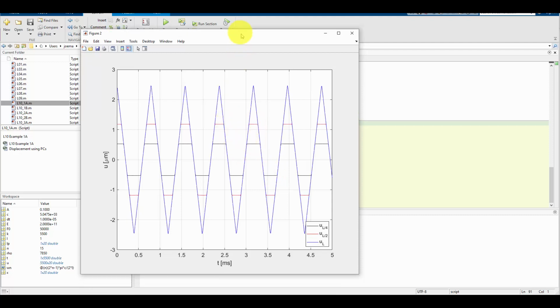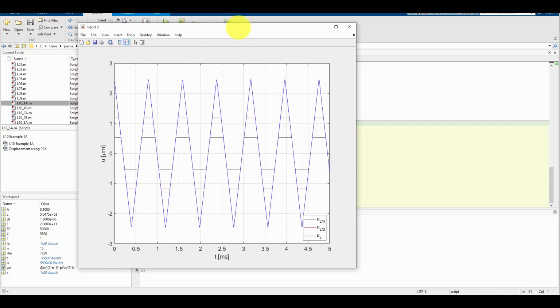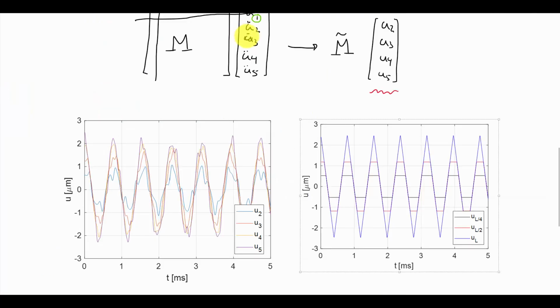So let's compare these more side to side though. All right, so I'm comparing just those output graphs now so we can get a nice qualitative assessment. We can do a more quantitative assessment later because this is just a demonstration of choosing an arbitrary number of elements and seeing how our system behaves. So if we look on the left, that's from the FEA we just did with only those 4 elements, 5 nodes, and the right is from the analytic solution from the previous section.